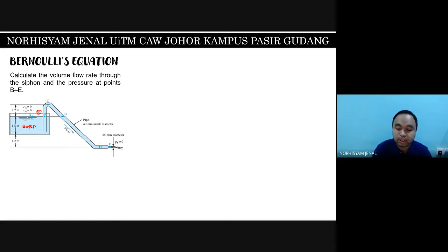Okay, in order for us to do this calculation, first we need to find out a few pieces of information. Number one, what is the pressure at point A? It is not asked here because based on our conditions just now, we assume the whole study is based on gauge pressure. So PA should equal 0, and PF also equals 0. Why?